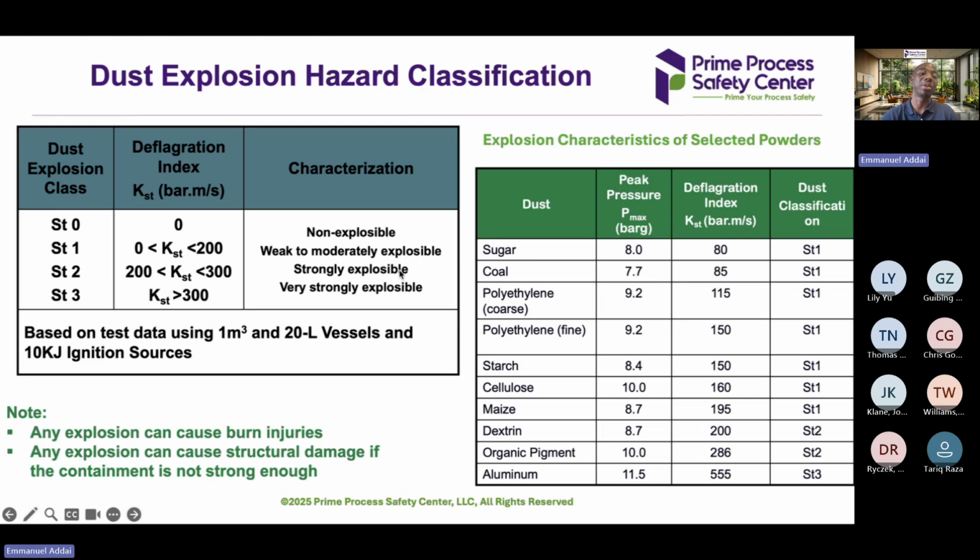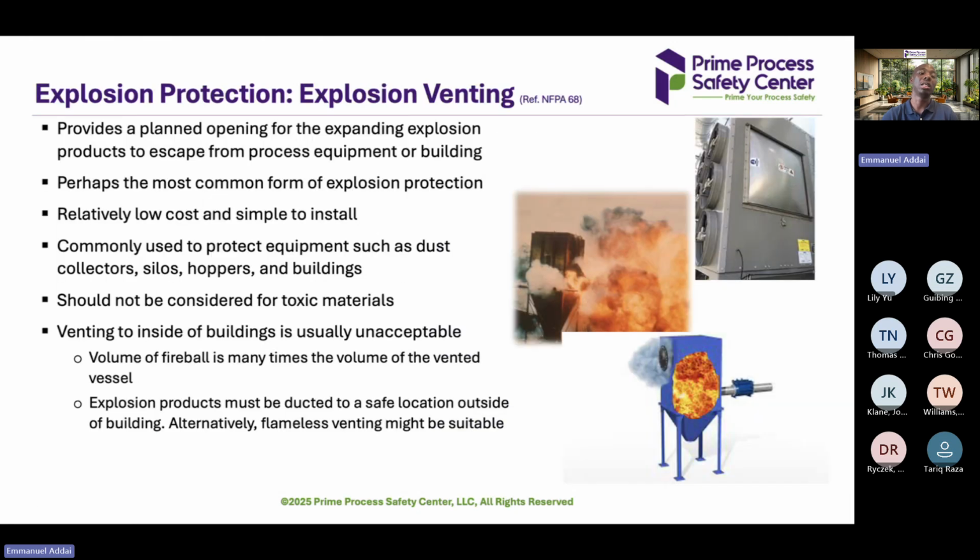So what are the applications of the explosion severity test? The first thing is explosion venting. If I have a baghouse or a dust collector, dust collectors are always prone to explosion. Unless you totally inert the whole system, in which case you don't need any kind of protection.